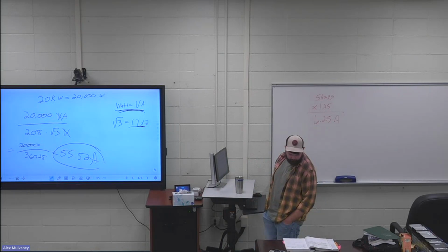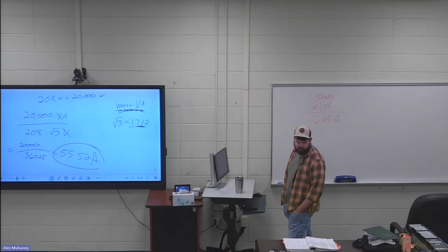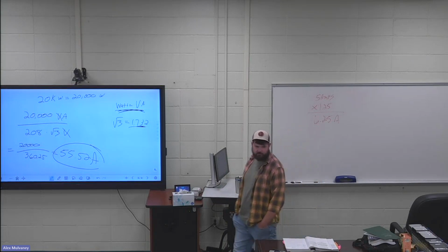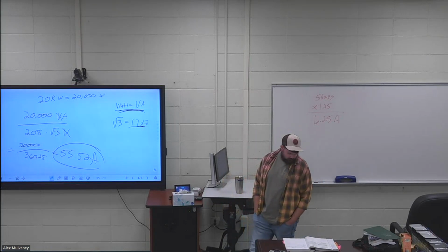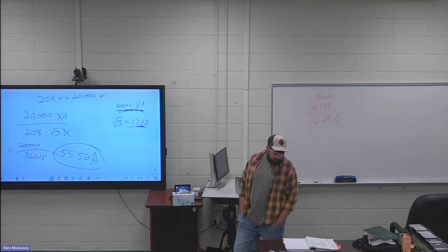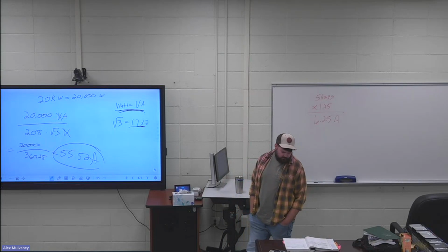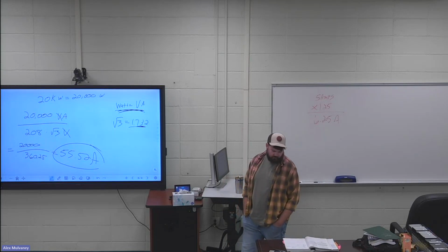Hint for number two: you need to use the equation with the R in it. You find the resistance in chapter 9, table 8. Instead of 2 times L times K times I, it's usually 2 times L times R times I over 1,000.